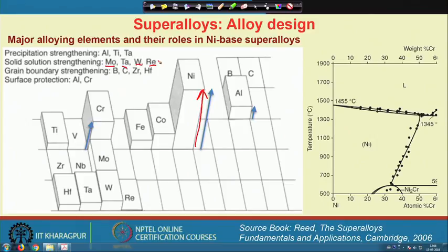So, I have solid solution strengthening, and one of the most important is precipitation hardening by the aluminides in the nickel base alloy. So, I have the Ni3Al precipitate, which is required for strengthening purposes. There we use aluminum purposely, so that we form this particular precipitate strengthening for high temperature, and sometimes titanium or tantalum is also added there. We prefer this kind of complex, or other, alloying elements to go inside the precipitate.